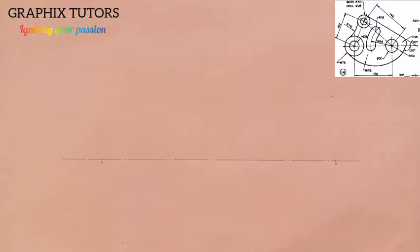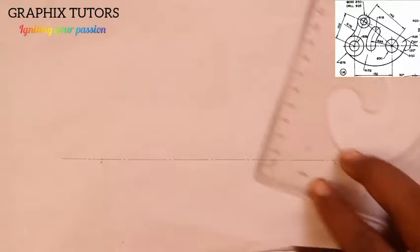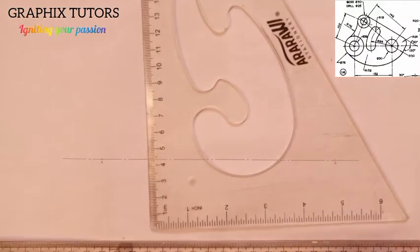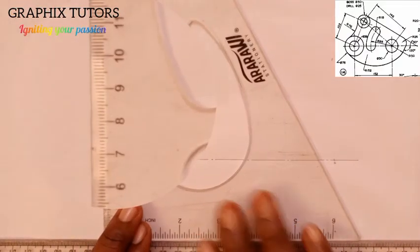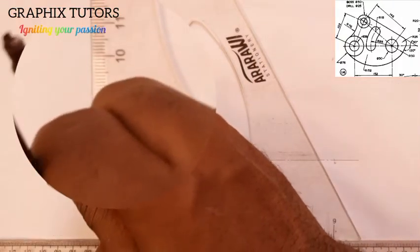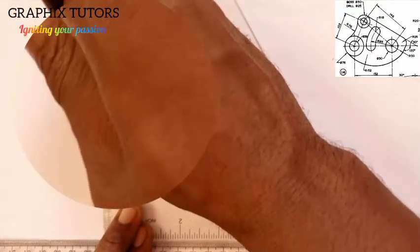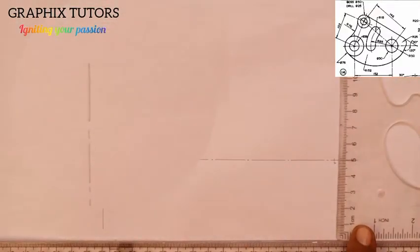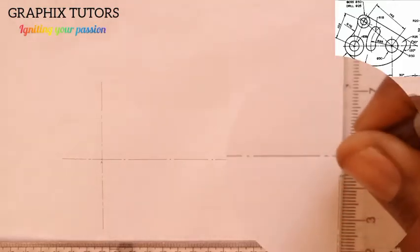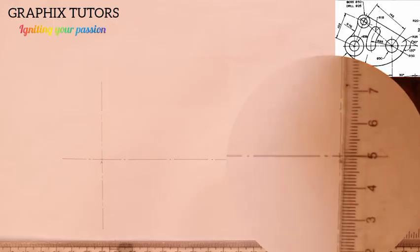I'll take my set square and place it on my T-square this way. Take it to that point and draw a vertical line this way. So I'll have another long one, short, long, short, long, short. That's our center line. I'll come here too and replicate the same thing: long one, short one, long one, short one, and long one. Now this is what we have here.